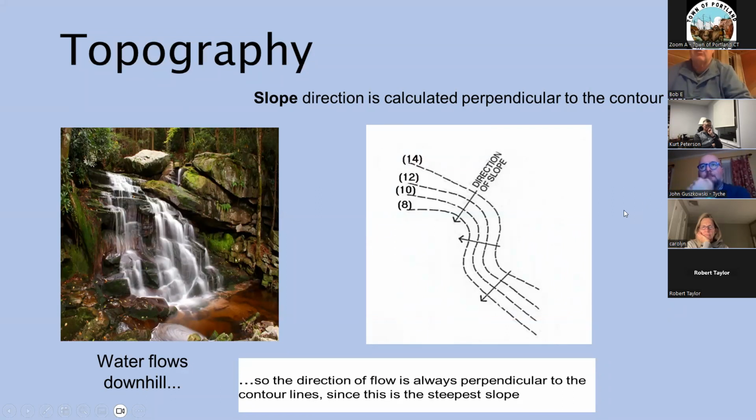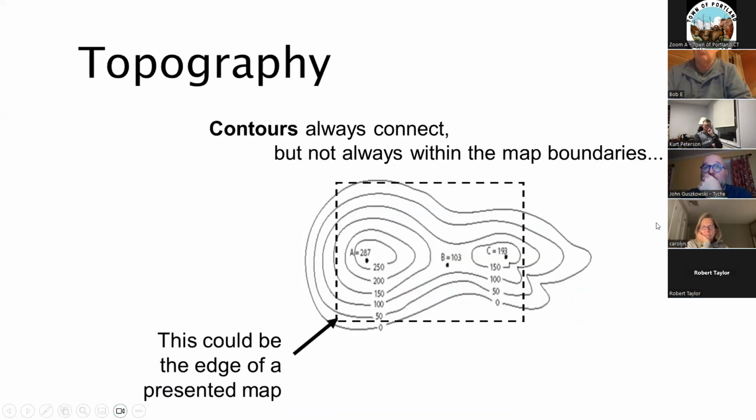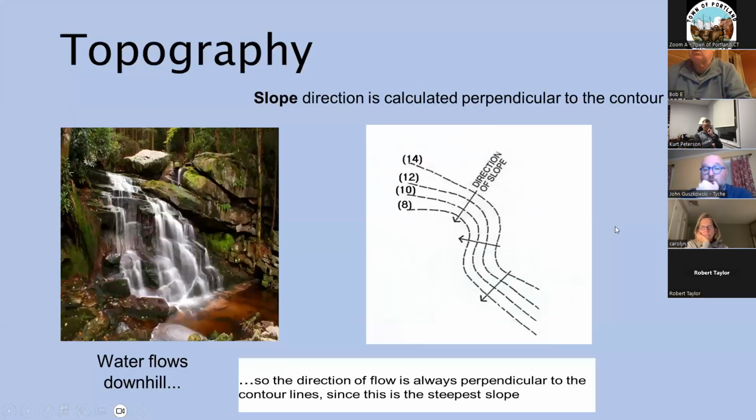So John, there must be a legend somewhere that defines how much the gap is between each contour line. Well, that's why we need to do measurements. Because topography is real life conditions. We're looking at a site plan from overhead, down from above, a two-dimensional view of a three-dimensional landscape. That's whatever scale it's drawn at. In the case of the previous map we looked at, that was 40 scale. So you can measure the distance between any two lines of contour using that same scale. Well, that's what we're going to talk about right now, is determining the slope.